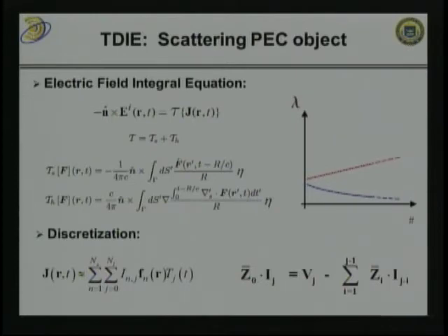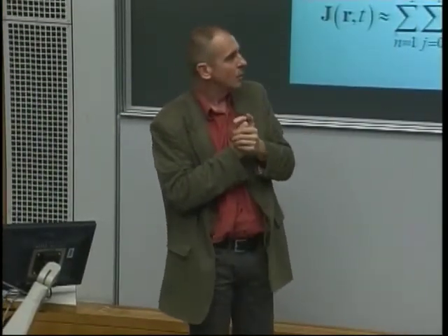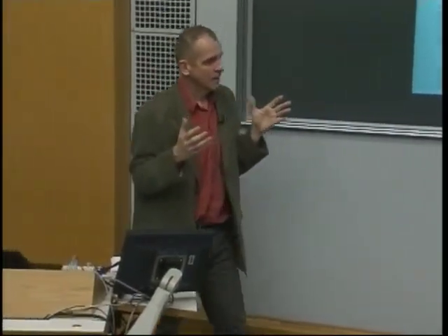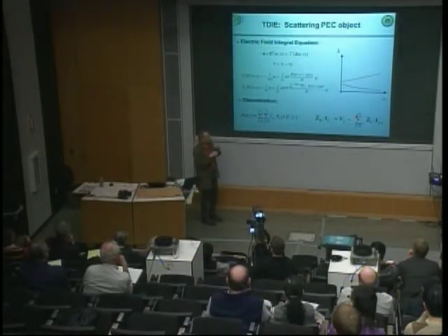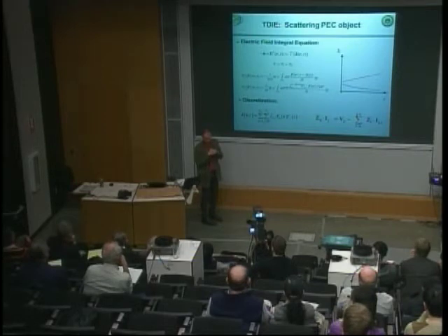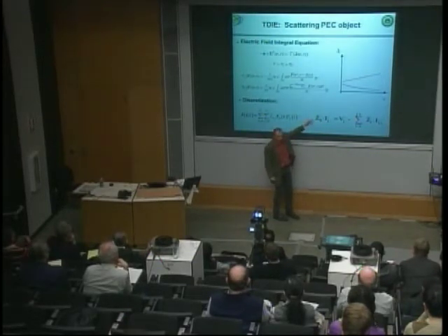And of course, everybody these days is interested in multiscale analysis. We're no longer interested in analyzing, say, scattering from a very large, smooth aircraft. No, we want to load that aircraft with very small antennas. We're no longer interested in analyzing a very simple and uniformly meshed bus for a chip. No, we want to attach to that bus vias and nonlinear components and things like that. We are interested in fine geometric details and their impact on the functionality of components. And so the ill conditioning of this matrix is more the norm than the exception.